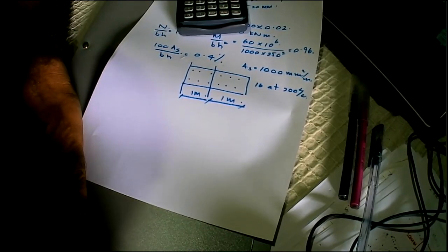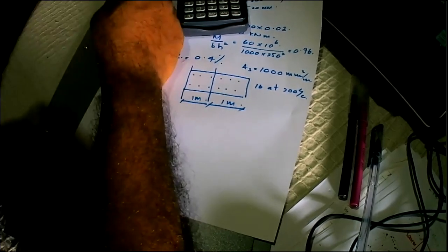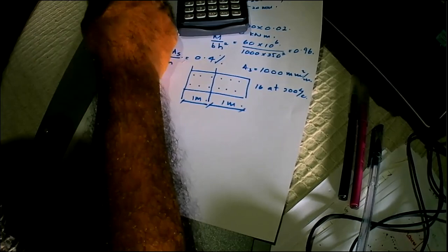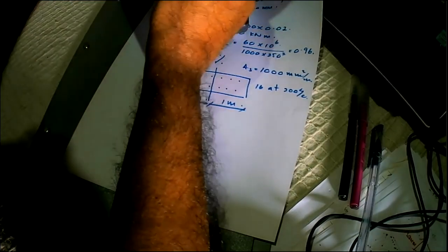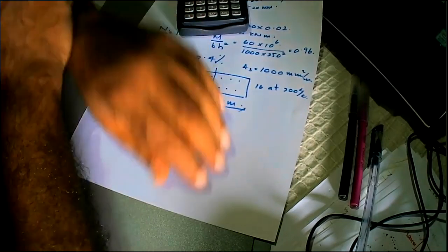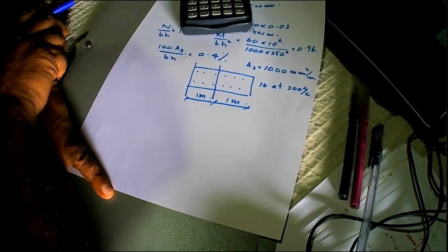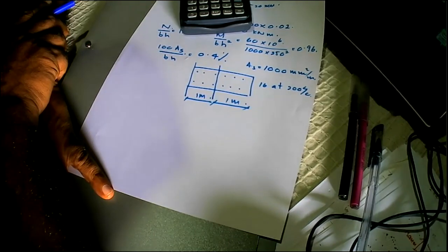So that's why these coupled shear walls are so important, because once you couple the shear walls, the bending moments will reduce, and the chances of tension occurring under the foundation can be reduced to a significant level. So basically you can ensure that no tension occurs under the foundation. Is that clear? We don't like tension in the foundation, no tension in the shear wall. That's why we have to make sure that reasonable load is transferred onto the shear wall, reasonable vertical load.